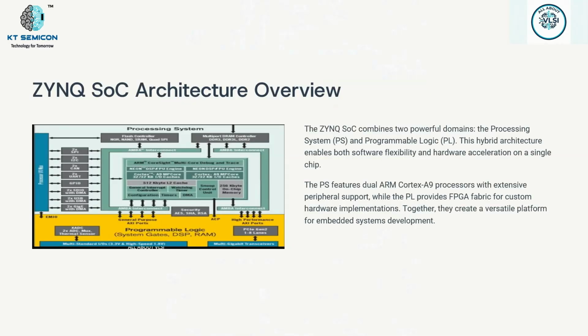So coming back to our course, let us try to understand this Zynq SoC architecture. As I've told you, the processor is present on a single chip, and it is a hard coded processor. We have classified our FPGAs into three types: FPGAs with no processor at all, FPGAs with a soft processor, and FPGAs with a hardcore processor present in them. This is the third category which we are going to have.